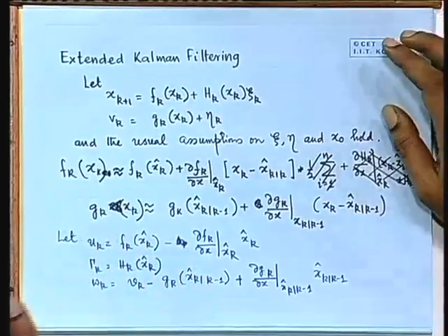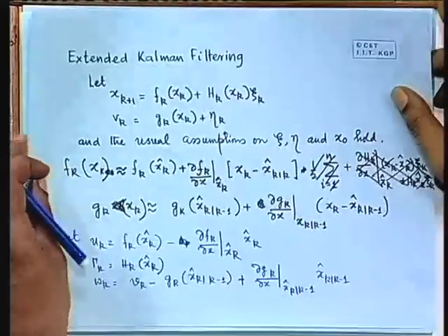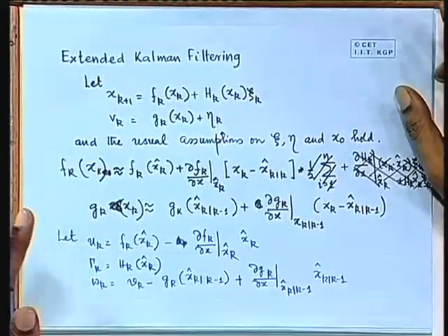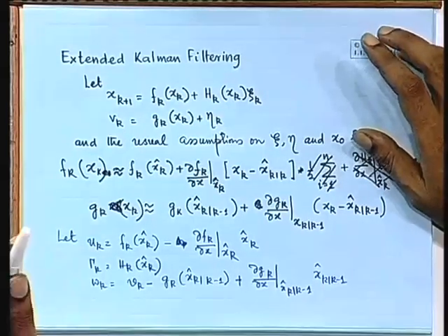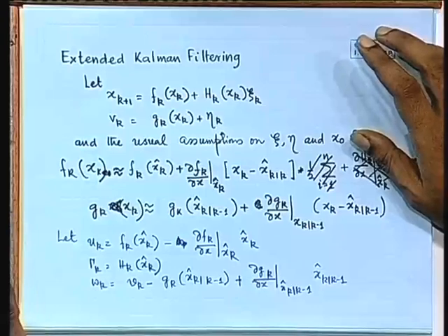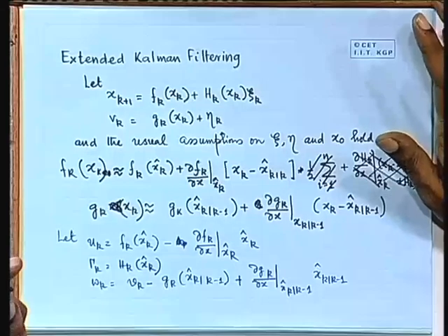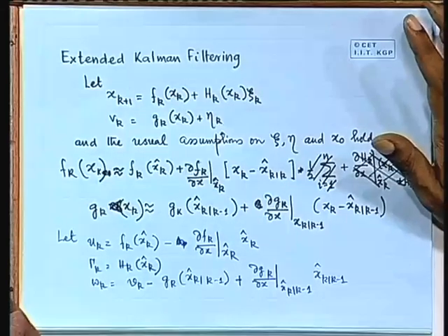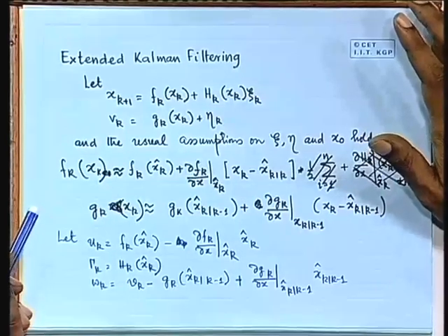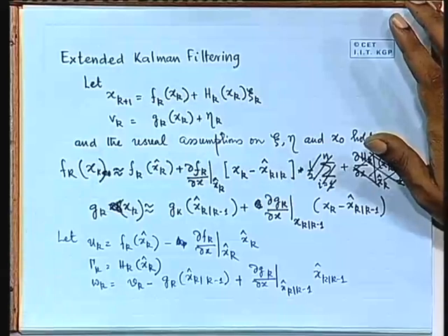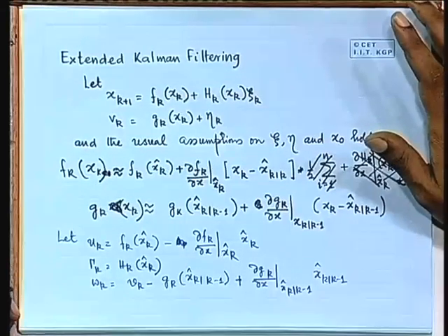To end, we want to just have a look at extended Kalman filtering for two reasons. Firstly, because a large number of estimation problems, especially in aerospace, often turn out to be non-linear. You see, we obtained a very nice linear model because we assumed that our measurement is in Cartesian coordinates. If our measurement was in polar coordinates, as happens often with radar, all our equations for theta and r would have been nonlinear differential equations, not linear.